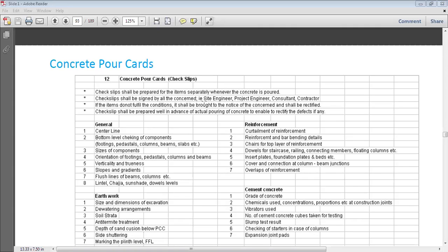But what we observed was that maybe we were lagging in the side shuttering portion, and the soil started sliding, that is, landsliding started. The depth of that excavation was more than around 10 meters. The soil started to slide and deposit from that area. At 11 to 12 o'clock in the night, our laborers called me and my seniors, saying no sir, landsliding has started, and it will totally hamper the freshly laid footing we have done.